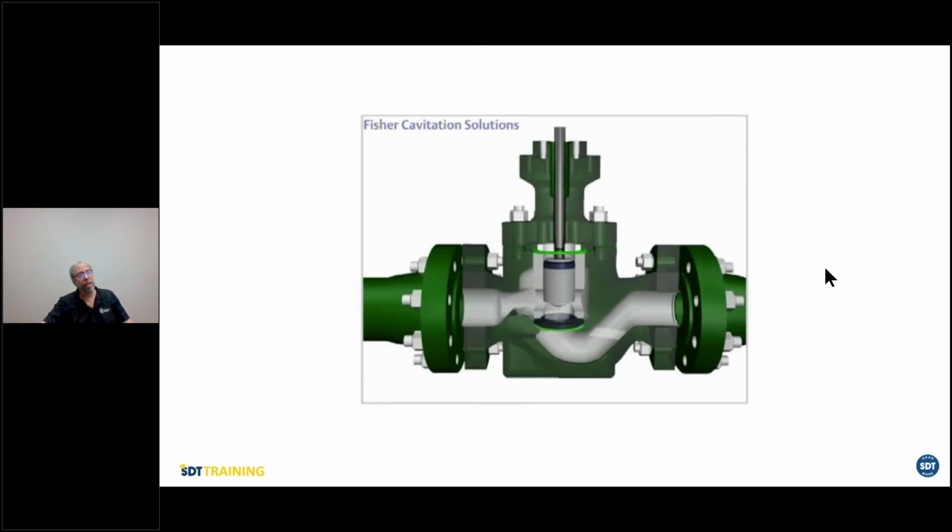As you can see, cavitation is a big problem on valves as well as pumps. By taking a measurement with ultrasound at the input and the output of any valve or pump, you can detect the cavitation, even flashing. So ultrasound is a very useful tool to do this, which you can't really use vibration for. I just want to show you what we can do with it.